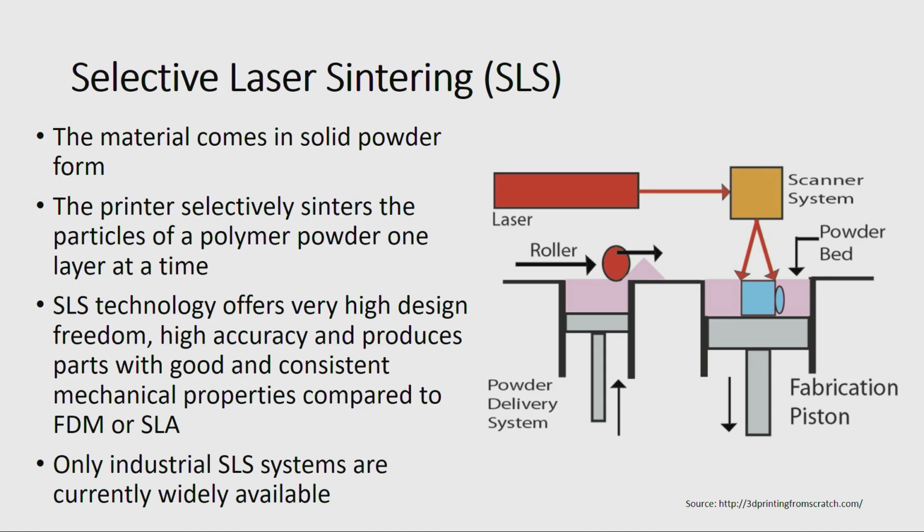Here one more advantage is, when the layers are built, we are filling the material powder to the total build volume. So there will already be a support material. Unlike in FDM or SLA 3D printing, no support structure is required in SLS 3D printing.